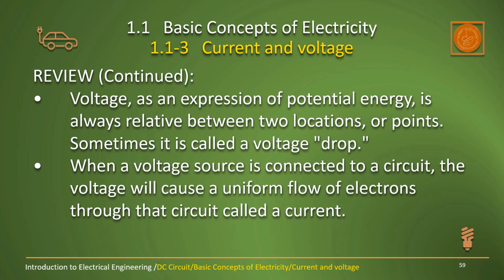So when the cable is running a long way, you have to calculate the voltage drop between 2 points to decide whether the cable size is big enough.